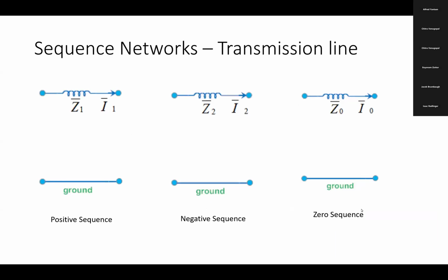So you are taking here zero sequence, positive sequence. This is a transmission line: positive sequence, negative sequence, zero sequence. Zero sequence must be 3 times the positive normal Z value. Okay, simple. Next is a generator.